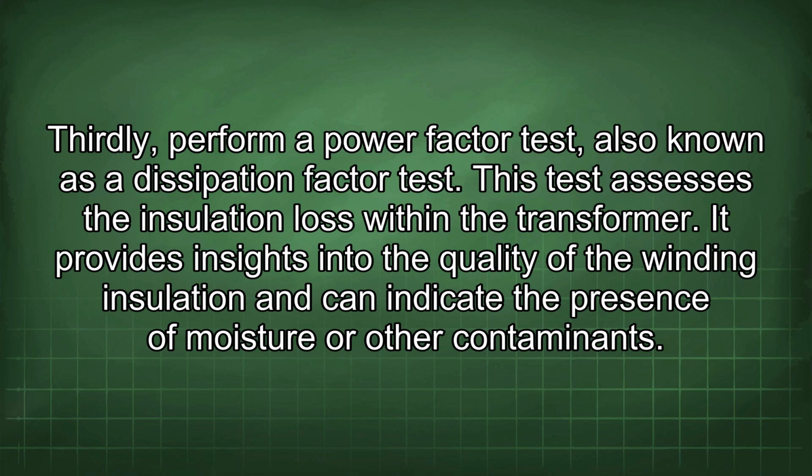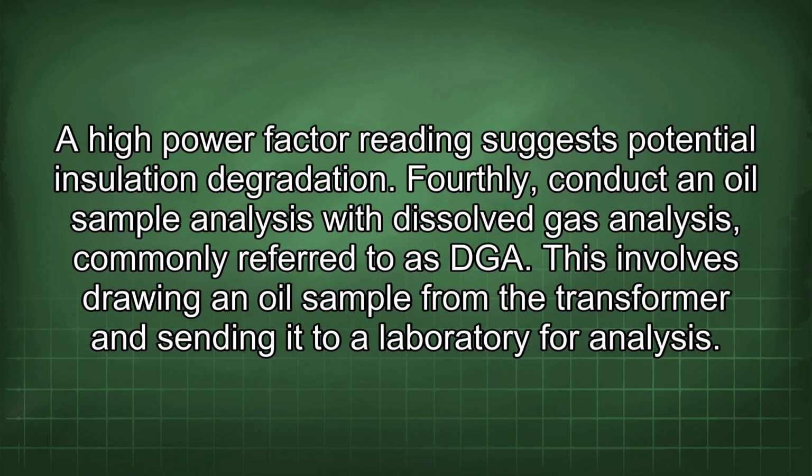Thirdly, perform a power factor test, also known as a dissipation factor test. This test assesses the insulation loss within the transformer. It provides insights into the quality of the winding insulation and can indicate the presence of moisture or other contaminants. A high power factor reading suggests potential insulation degradation.